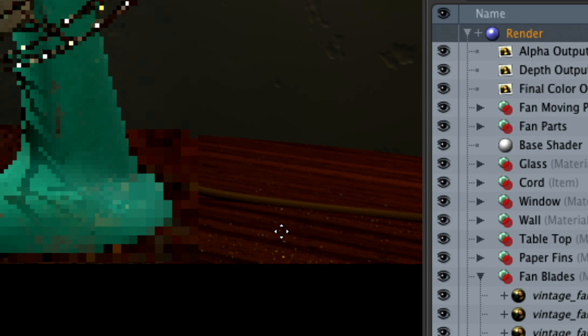There's two basic ways of removing the grain. First and foremost, cranking up all of your render settings. By blasting out a lot of rays into your scene, you'll eliminate a lot of that grain. However, what's going to go up? Your render times. Your render times are going to skyrocket into something that's just not possible to deal with.